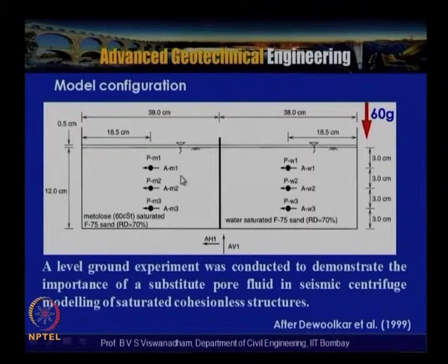These are the accelerometers with metolose as the pore fluid, and these are the pore water pressure transducers. So here metolose of 60 centistokes kinematic viscosity was considered because the model is at 60 gravities.